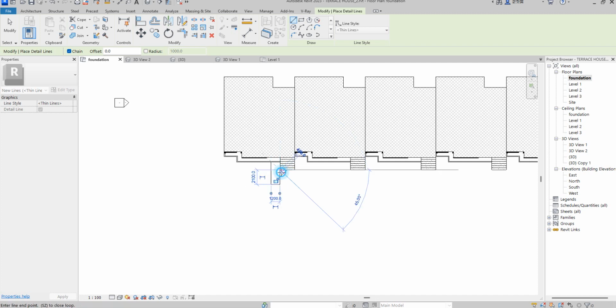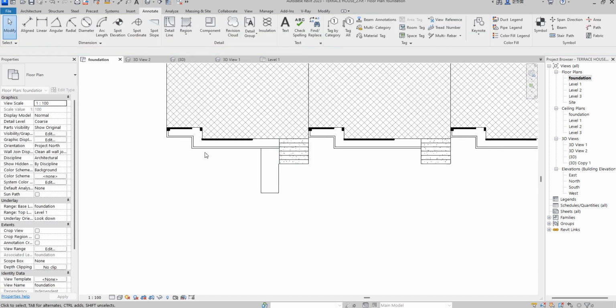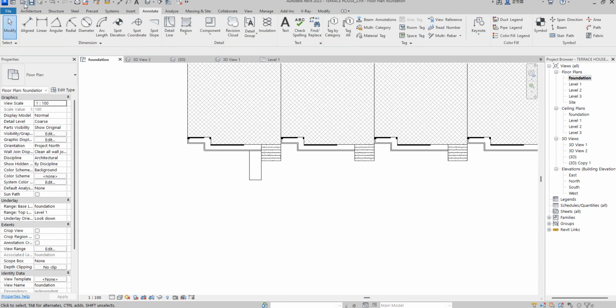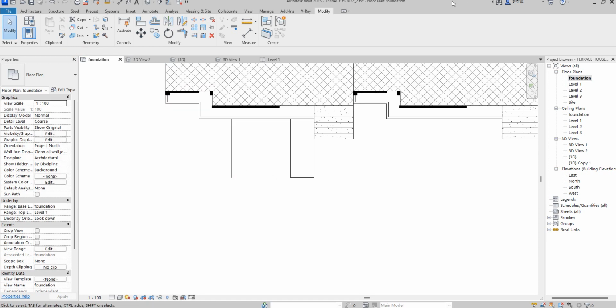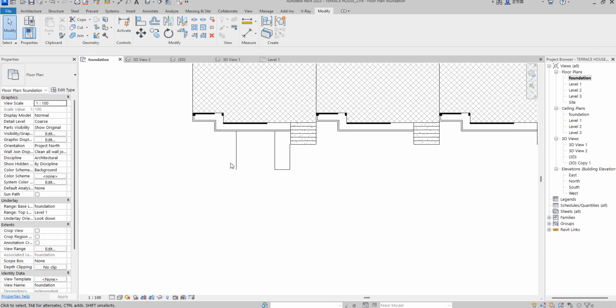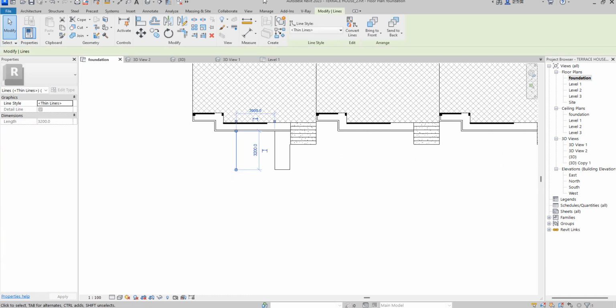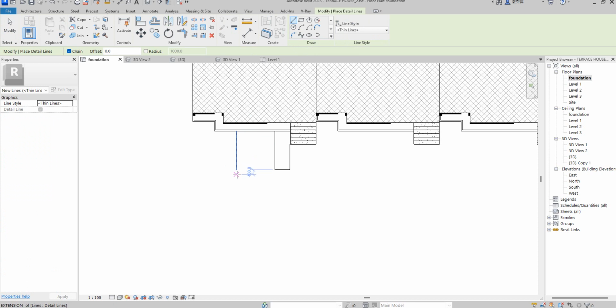I want to create a site plan here now. So I'm having a parking lot, so let's say modify. So I'm going to have an offset of 3000. So that is like car space for one family. I think I prefer that only one car be allowed into this position. So as I've done with this one, that is the car point. So I'm going to do this one now and add some little level of aesthetic value.